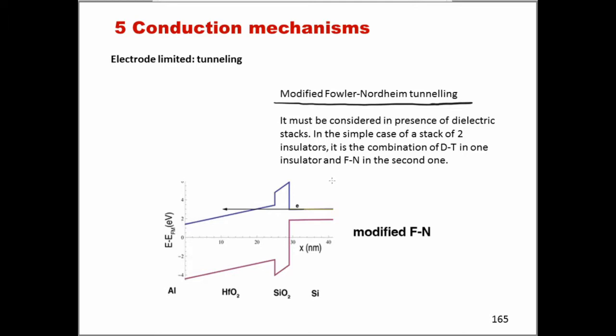This type of mechanism is actually a combination of direct tunneling and Fowler-Nordheim, and as I said, is particularly evident and must be taken into account when we are dealing with dielectric stacks.